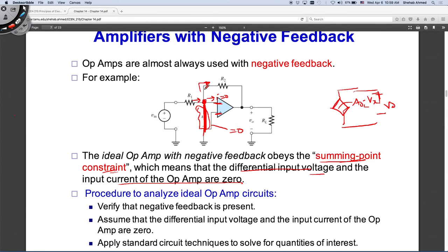Does this make sense? So this is not really connected. It is an open circuit, but the voltage is zero. So I can still do Kirchhoff voltage law. If this is the voltage, and I want to find the input current, what does the current here look like? It's this voltage divided by this resistance, and this is a voltage, zero, plus Vx, right? V output equals, this is the current, the voltage drop is in the opposite direction, right? So it's the voltage drop here, V input